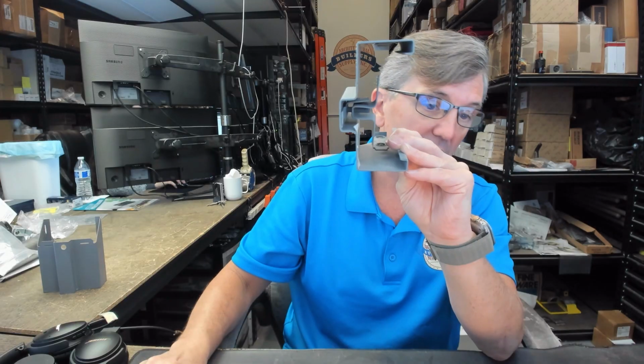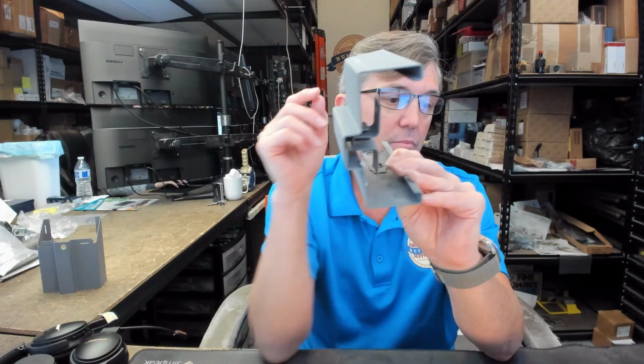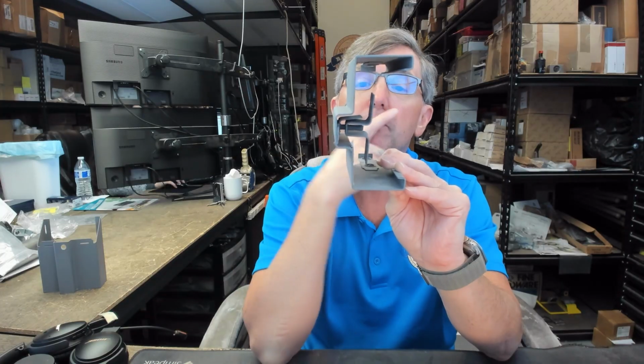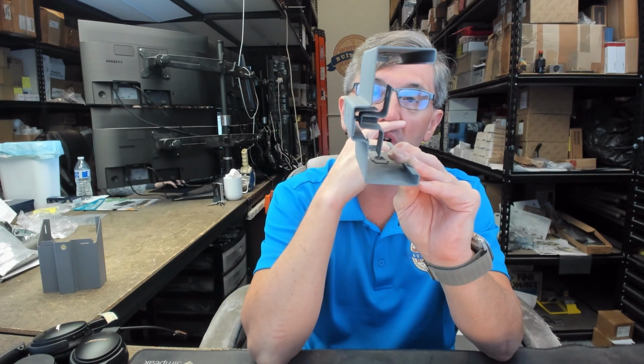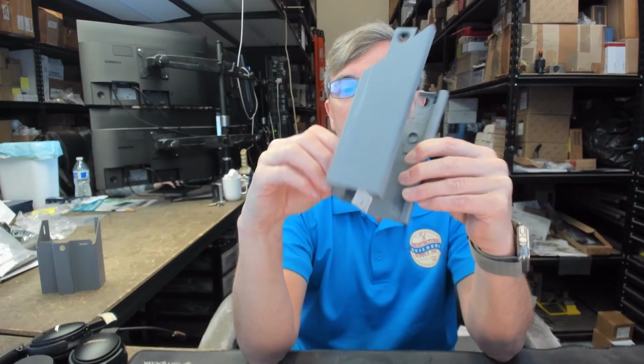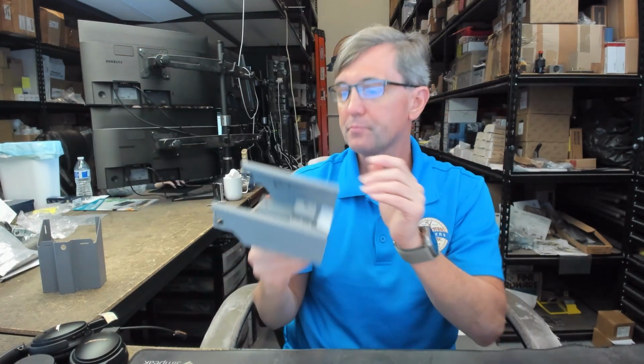So your rough opening really needs to be a different size for that sort of application. It needs to be a size that will accommodate your cased opening frame. And because you're moving that over, and that's generally 5/8, you're going to have a bigger rough opening to get that installed. But cased opening frames are fairly uncommon.